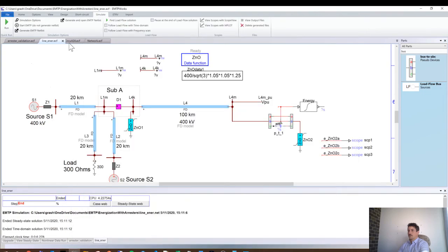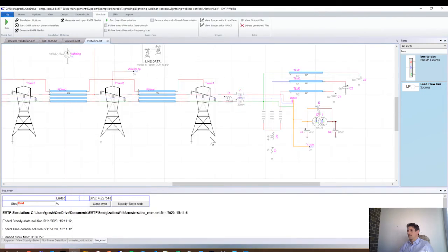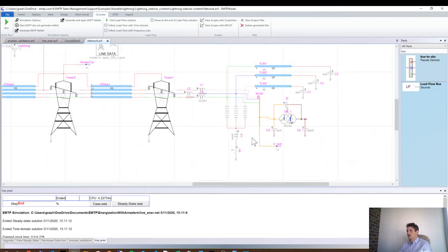Okay, so this is for switching. For lightning now, it's very similar. So you connect your three arrestors here. Here we cut the 3-phase into 3 because it's important to model the length of each conductor. Often the 3 phases are not exactly next to each other. There are some conductors in between and the neutral and all that. Everything should be modeled.